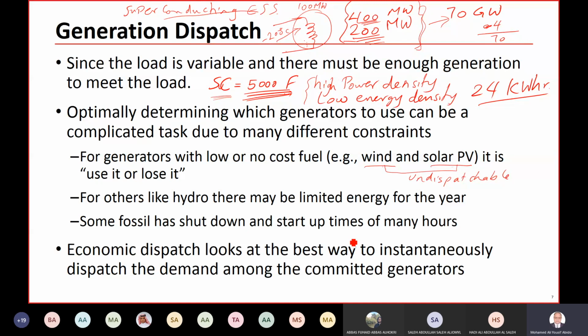In no time, the wind power could reach zero. If you have wind at 5 meters per second or 10 meters per second, and you generate 100 megawatt, maybe in 1 or 2 minutes the wind stops, and then you have the output power very, very low. So the ramp up and the ramp down here is very sharp for wind and also for solar PV.